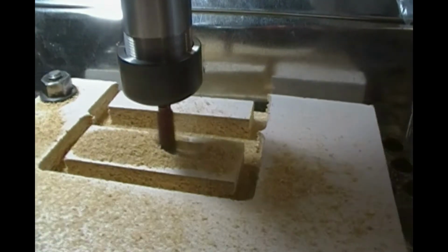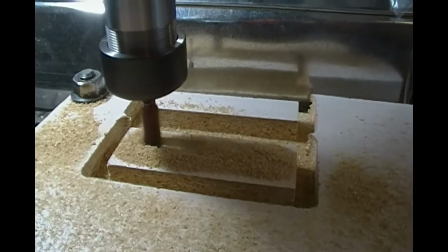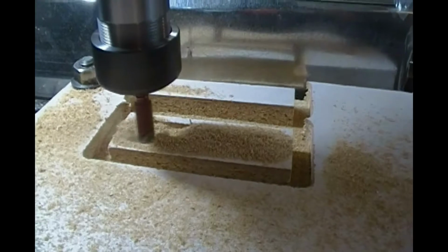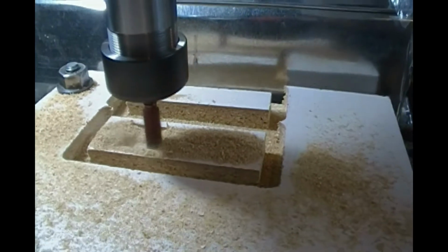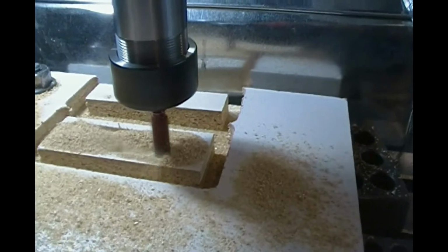As a precaution, I would prefer to make the first cut in the midpoint of this pocket, leaving thinner cuts along the long sides of the pocket, creating less stress on thin borders and no need to clean up the bottom of the pockets afterwards.